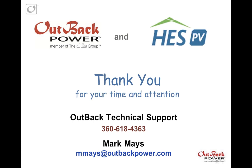And down below we have 8 slots. Typically people use those for the DC side, like if you're using charge controllers with PV, our ground fault detection interrupter circuit breakers. They're all panel mount breakers. These aren't DIN mount. They're standard Outback panel mount breakers. So to summarize, 10 on the top, 8 on the bottom.